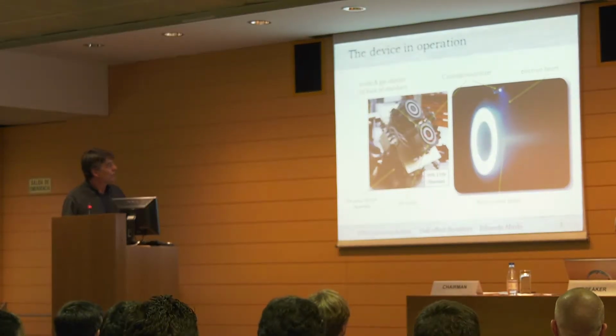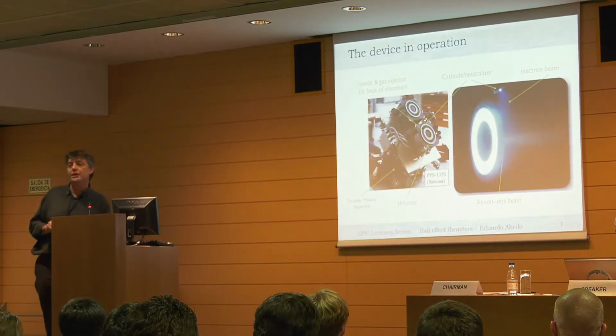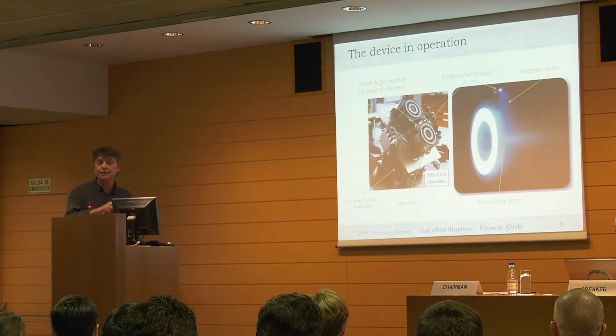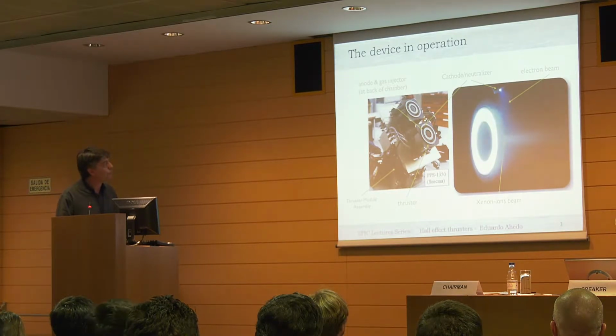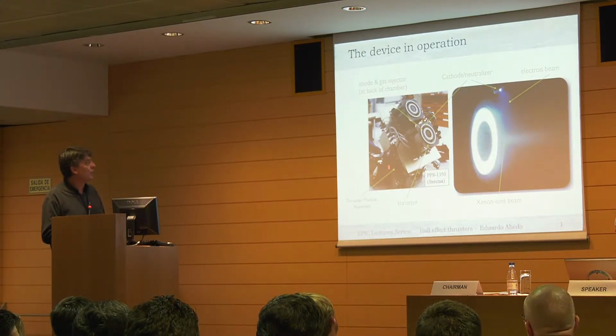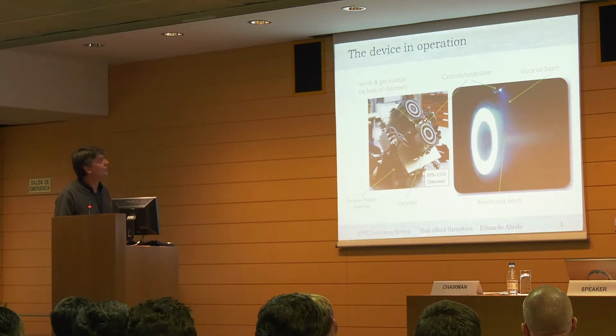Okay? These white walls are made of ceramic material. Normally it's boron nitride or boron nitride with something. With this ceramic material, we have a better control of the electric fields that we have inside the thruster. You can see here that we have a couple of hollow cathodes for redundancy in this case. And well, we have then all the thruster module assembly to control all the parameters and the functioning of the thruster.